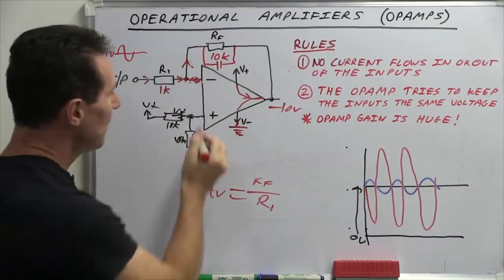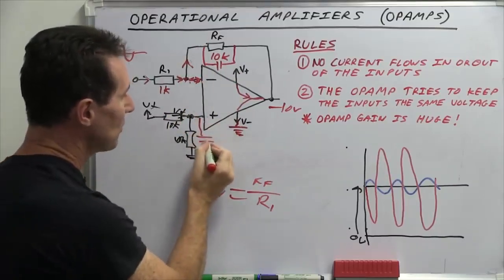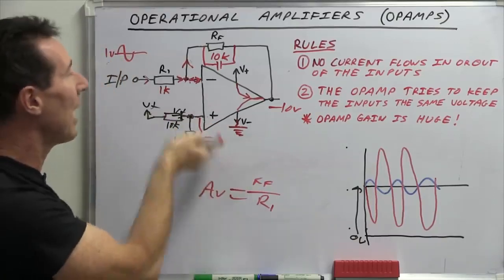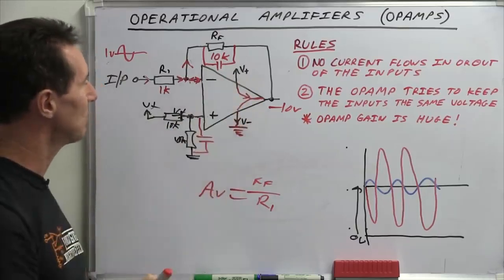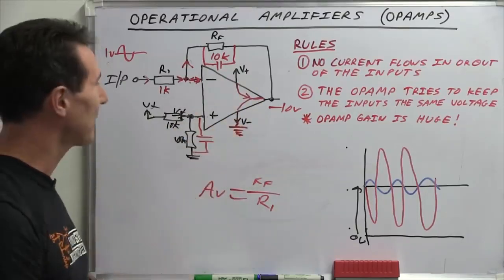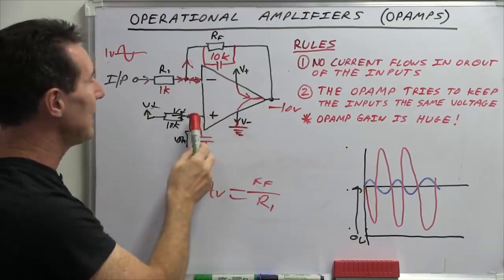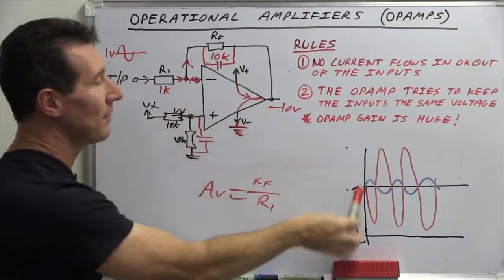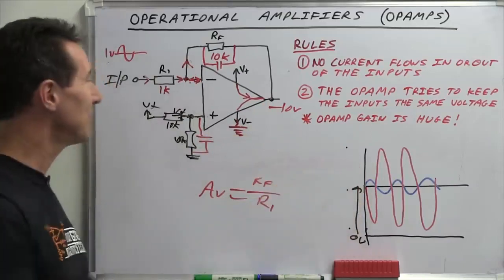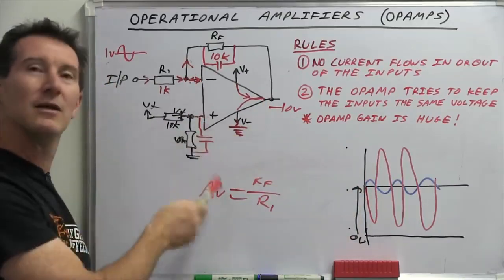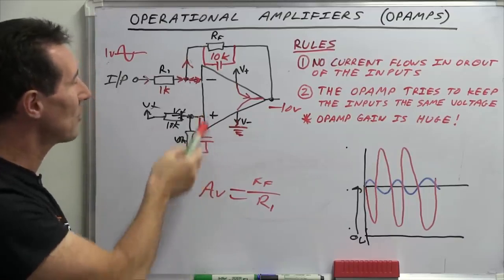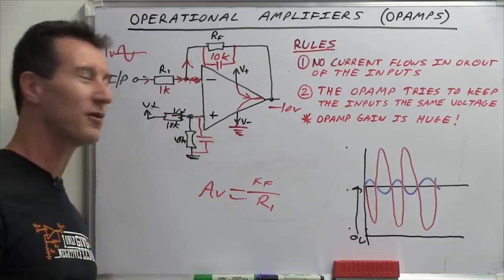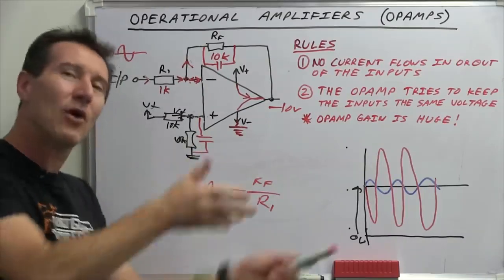And likewise, you might see a little cap across something like this, for example, if you are offsetting this thing using a single supply like this. I won't go into the details, but basically any noise on this point here will be amplified and picked up on that virtual ground, so you'll get noise on your output signal. So you might stick a big 1 or 10 microfarad cap across here, for example, and really make that virtual ground really noise free. But hey, that's beyond the basics.